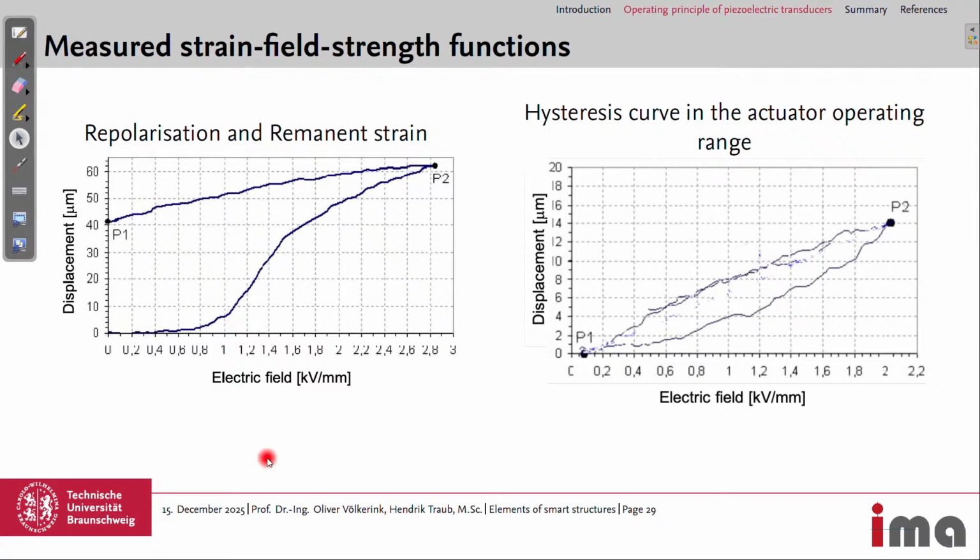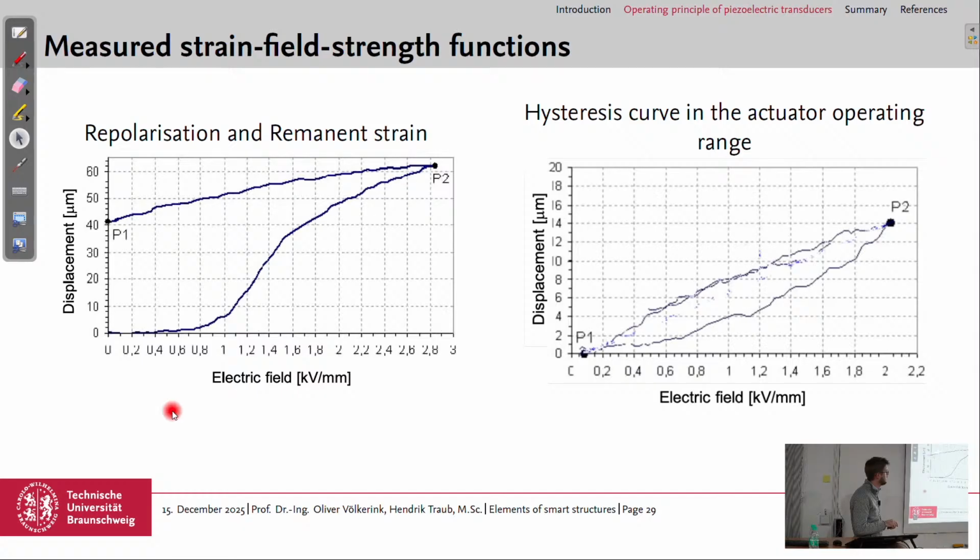This quantity is specific to the thickness, so you multiply it with the thickness of your material, and then you get the voltage you need. So if you have 0.5 millimeter thick material, you only need 1.4 kilovolts. And if you have material which is 2 millimeters in thickness, you would need 5.6 kilovolts. Distance between the electrodes.